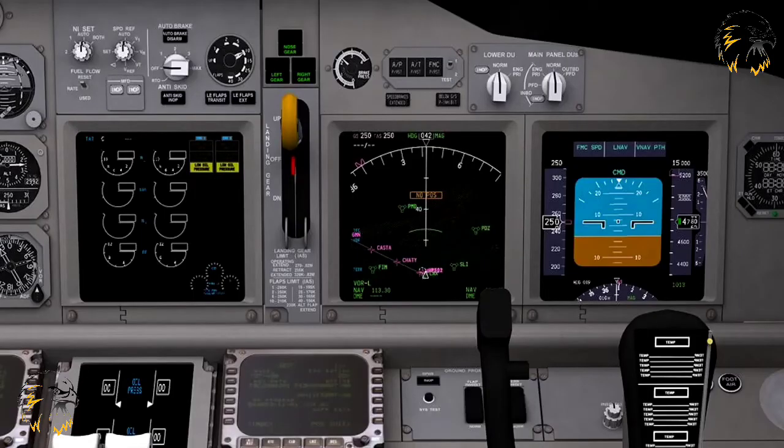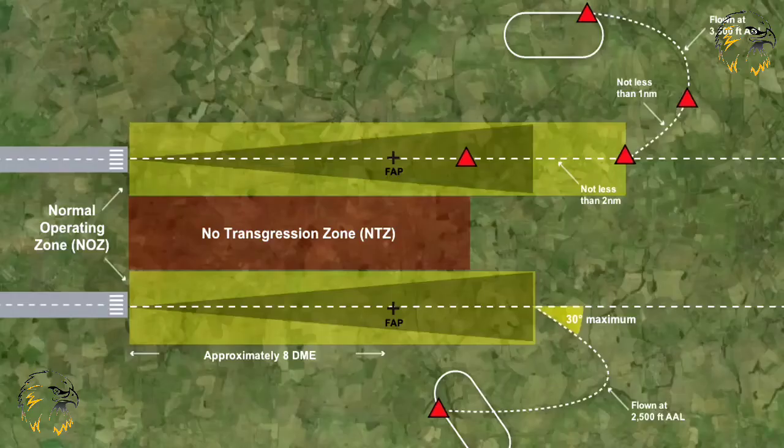To conduct parallel approaches, aeroplanes must be fitted with the normal IFR avionics, including full ILS or MLS capability. Where independent procedures are in force, all aircraft are to be advised accordingly on initial contact with approach control. Regardless of weather conditions, all approaches are to be radar monitored by radar controllers specifically dedicated to that role, using a dedicated radio frequency.